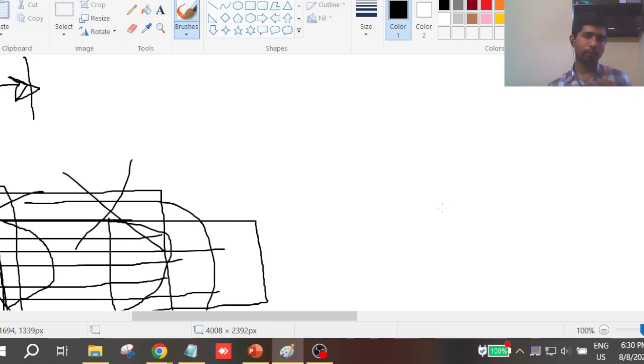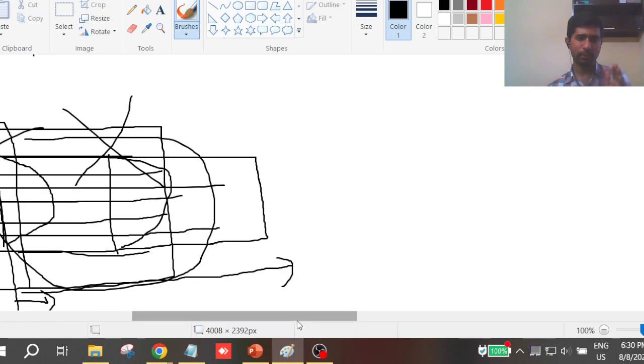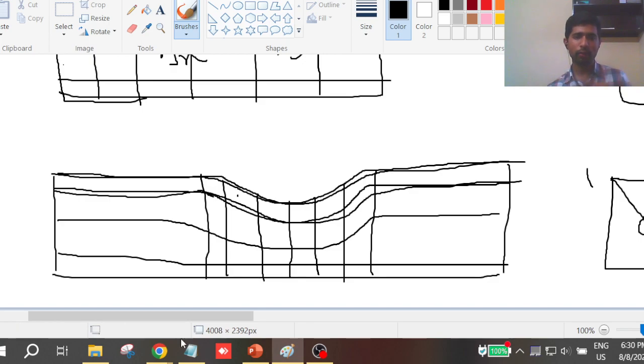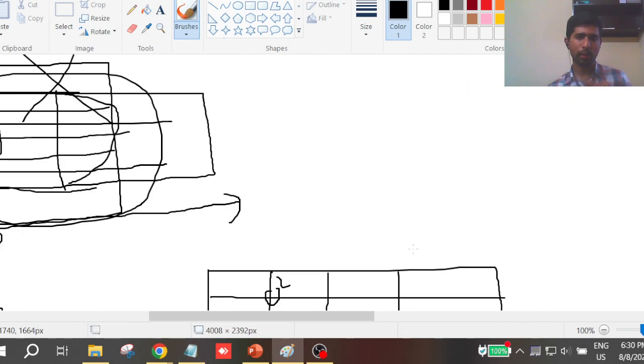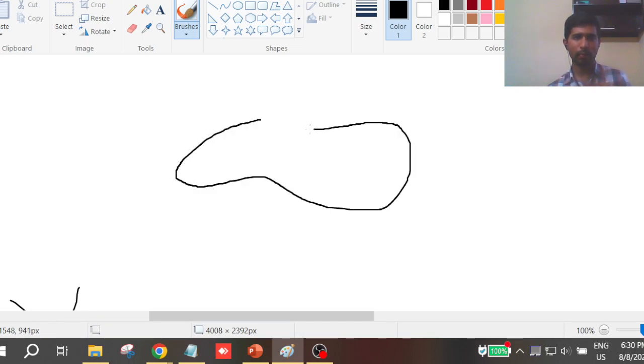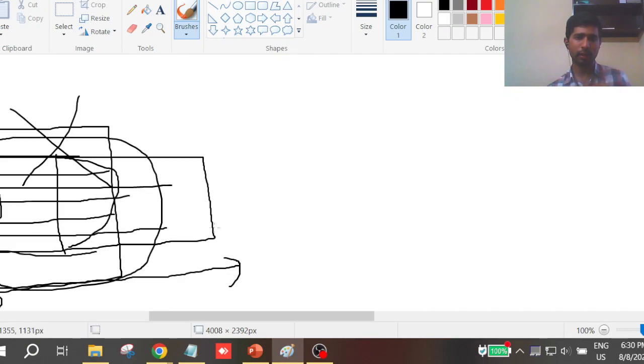One thing which I forgot to say is that for these simple examples you can go with a structured mesh, or even a curvilinear mesh for this blocked channel. But if you have a very complex, very random kind of domain, and inside that you again have some solid particle, and this is your flow domain, it becomes very difficult to generate curvilinear meshes.